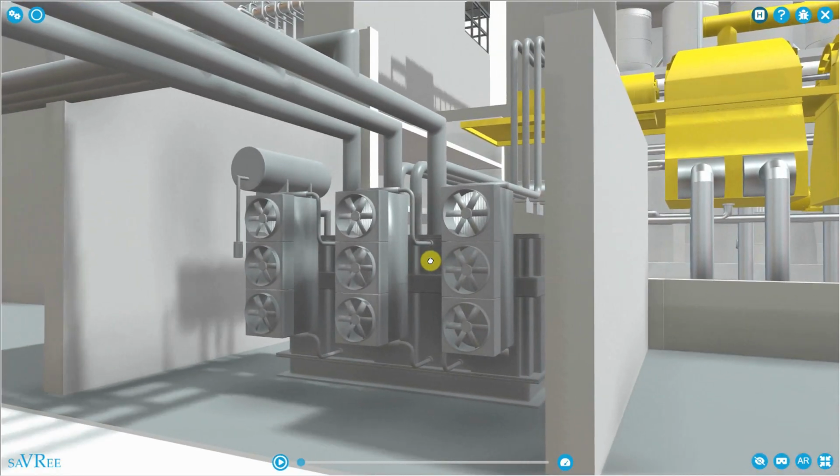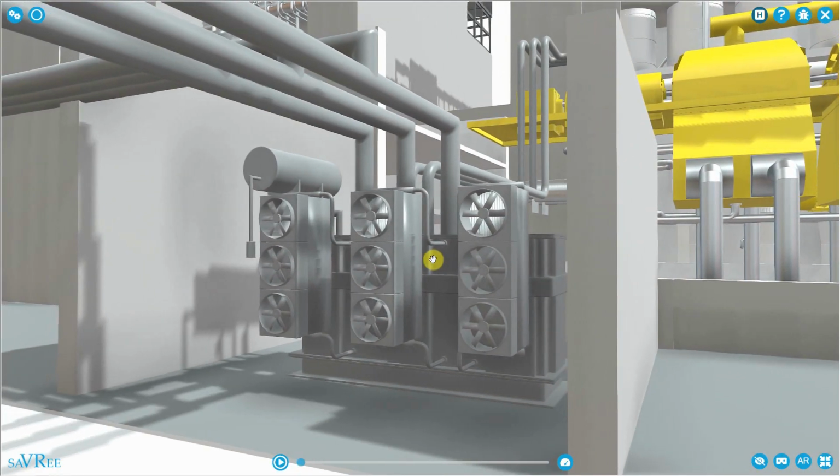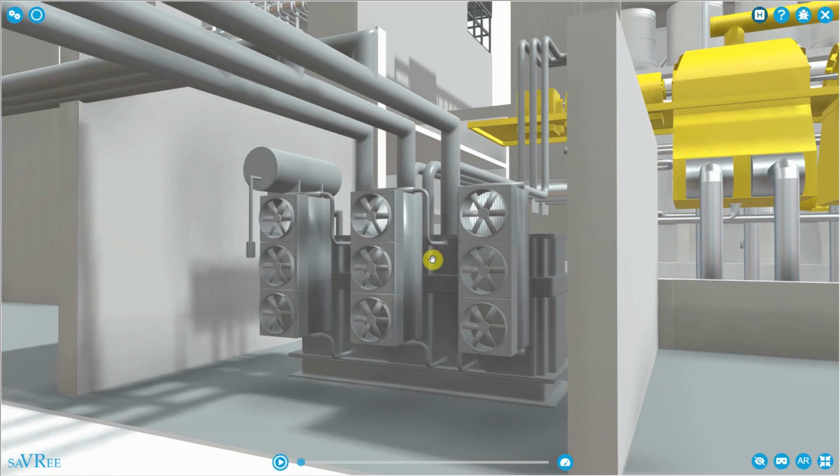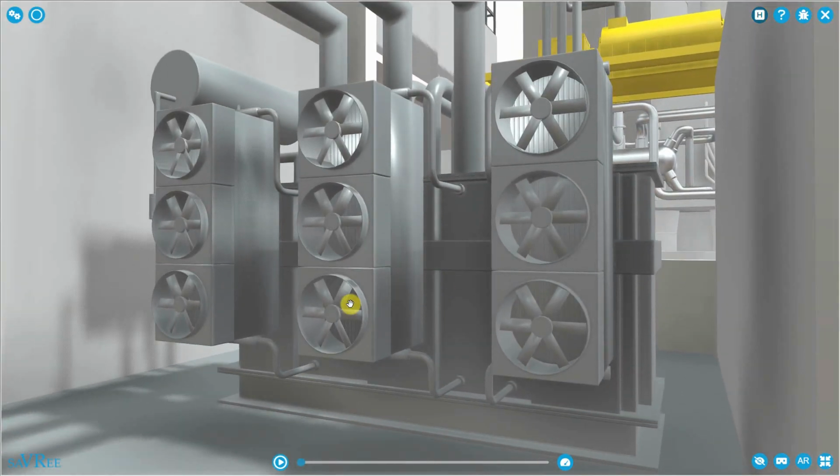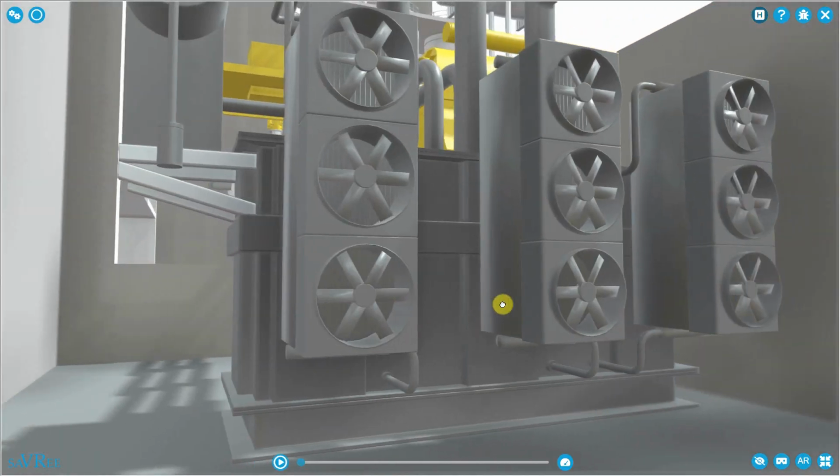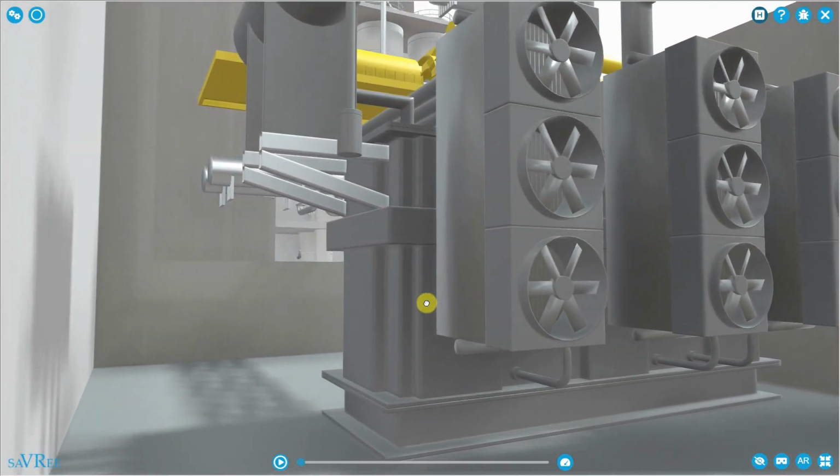This type of transformer is a liquid insulated conservator type transformer. The transformer components are sitting within a tank, and the tank is full of mineral oil, usually. Sometimes it's full of a different type of oil, such as a natural ester oil, but the mineral oil types are by far the most common. Over 95% of all liquid insulated transformers use mineral oil.